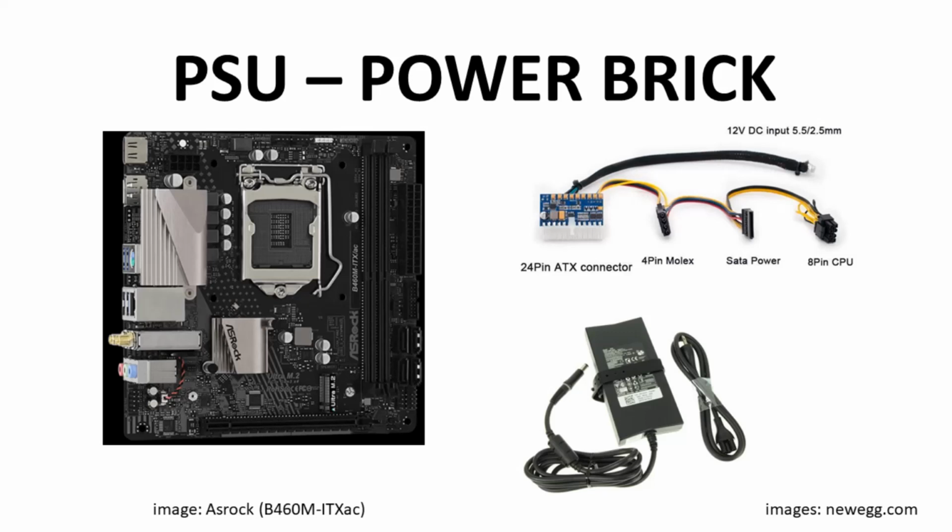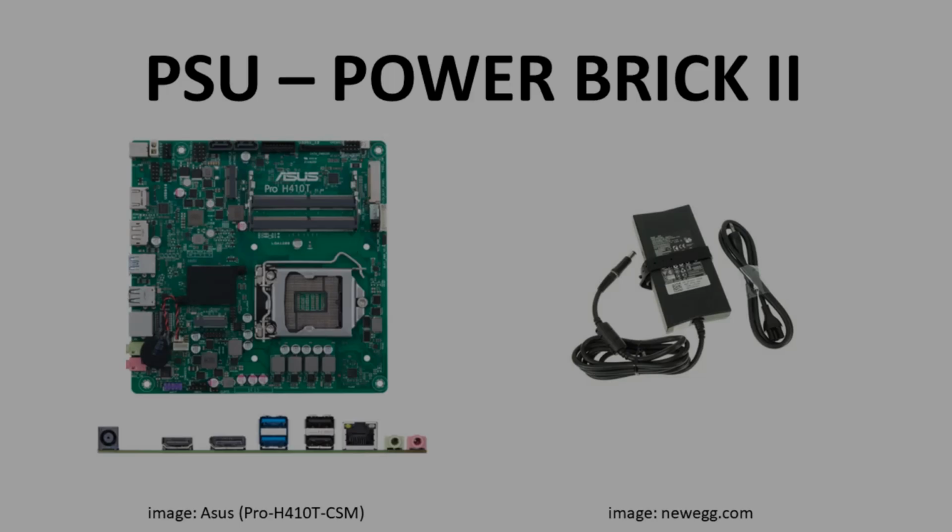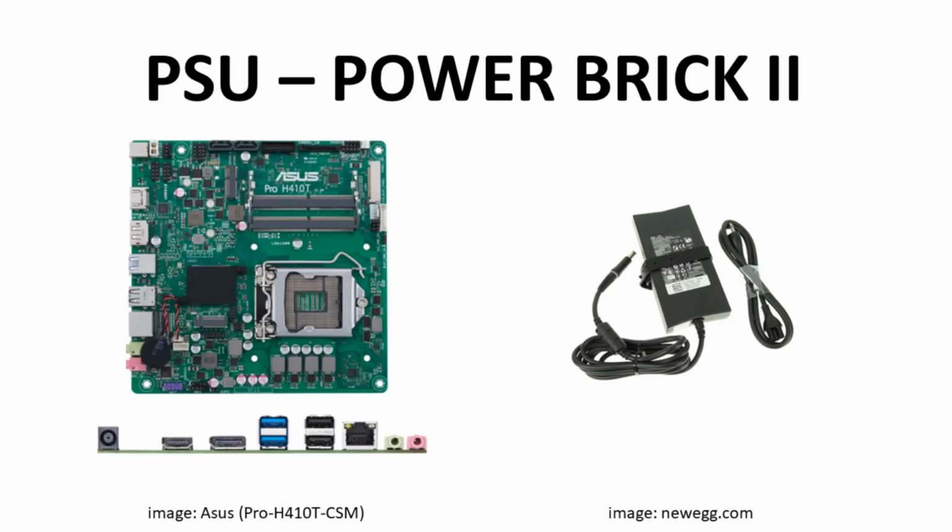This is all fine for a mini-ITX board, but how about a thin mini-ITX board? The thin boards are very different. Here is a thin board. Note that there is no 24-pin connector on the back edge of the board. Power delivery to thin mini-ITX boards will always involve an external power brick.